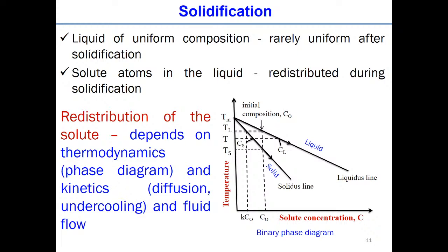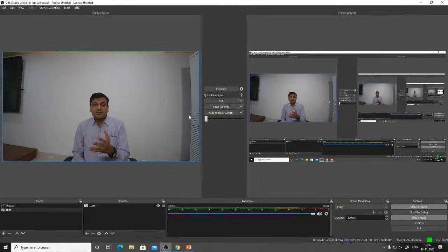It means the temperature can be lower than the liquidus temperature, or lower than the solidus temperature. Combining these two effects, the supercooling happens in this particular zone because of the solute concentration variation in front of the solid interface. That is normally called constitutional supercooling.